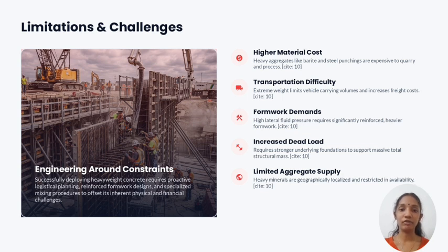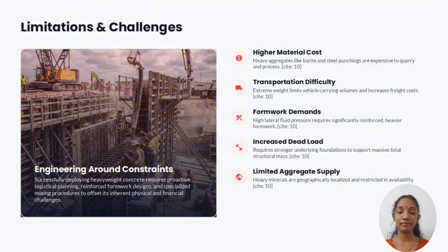Third, stronger formwork is needed to withstand the higher pressure during casting. It also increases the dead load on the foundation, requiring stronger structural support. And heavy aggregates are not available everywhere, so supply can sometimes be limited.